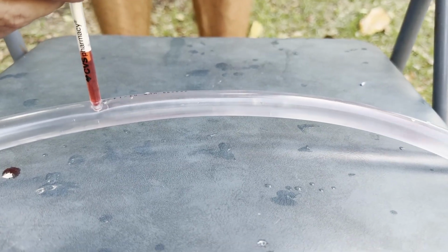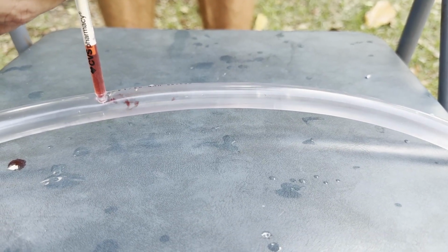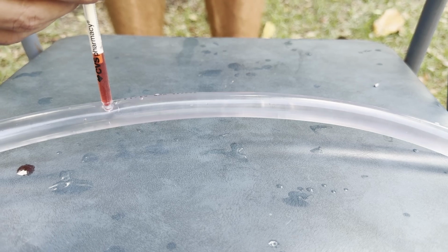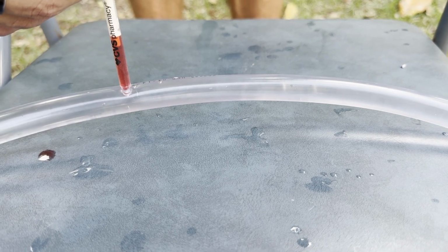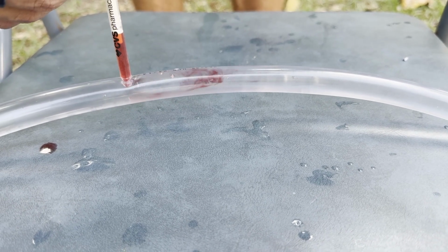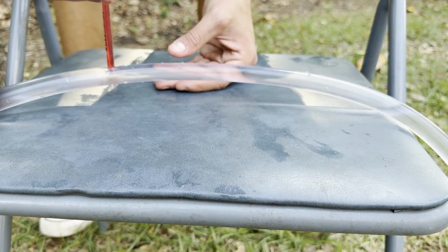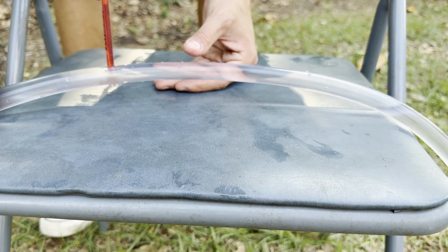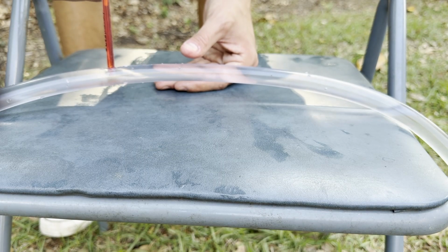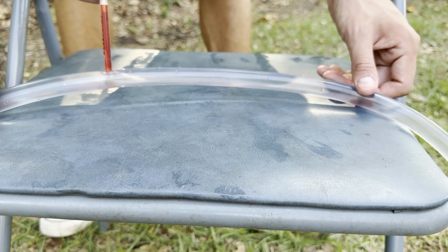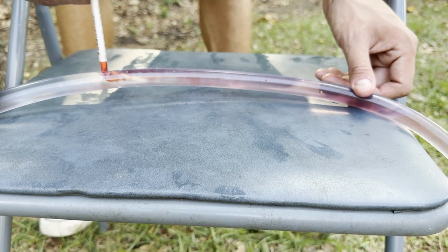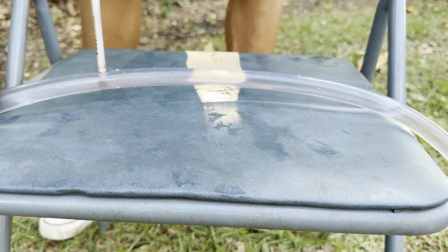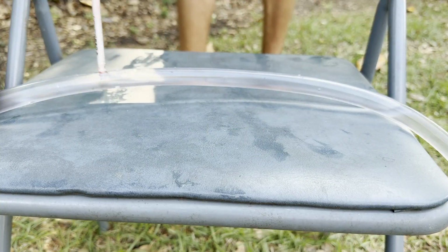You can see here that the dye is becoming unstable and it's beginning to fluctuate and disperse later on down the pipe, indicating the onset of turbulence. And in this last clip, it is a high Reynolds number, the flow is turbulent, and the dye very quickly mixes and disperses throughout the fluid, indicating chaotic motion.